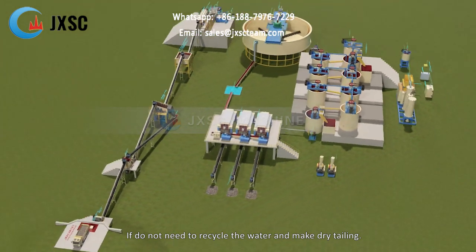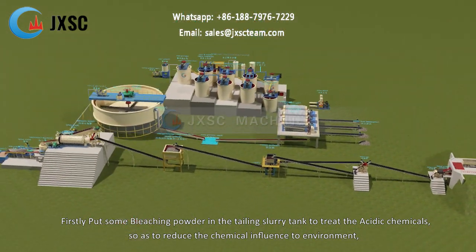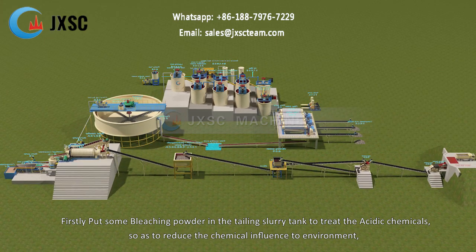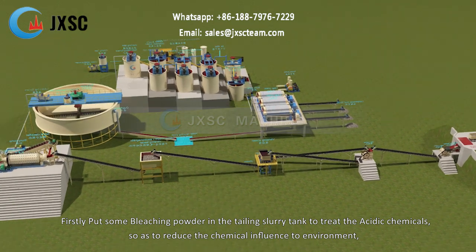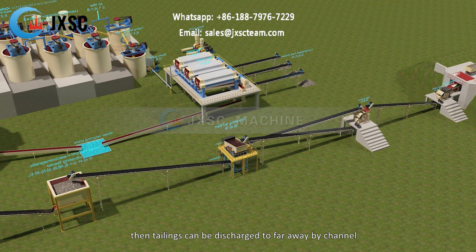If you do not need to recycle the water and make dry tailing, firstly put some bleaching powder in the tailing slurry tank to treat the acidic chemicals, so as to reduce the chemical influence on the environment, then the tailings can be discharged far away by channel.